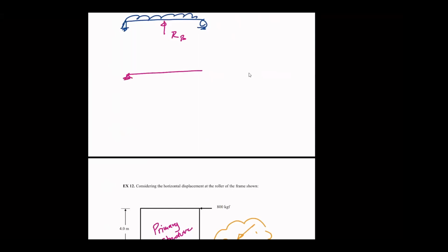you are going to have to, okay, here's your beam. If you want the mid-span deflection, you need to draw the deflected shape and then do this. Your deflection is this one, but then let's say this is A, B, and then this is C. This becomes TCA, which is not the deflection.